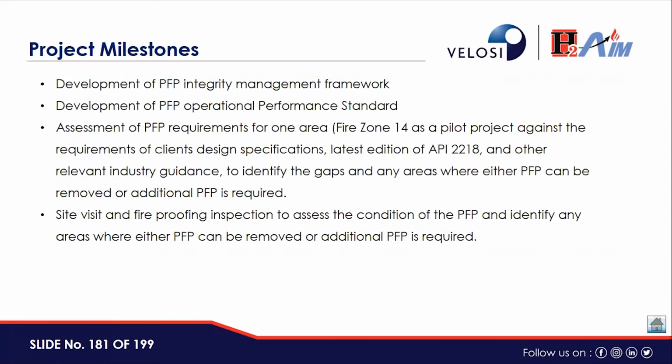These were the project milestones. Development of passive fire protection integrity management framework. Then development of the passive fire protection operational performance standards. Then the assessment of PFP requirements for one area, which we have selected as fire zone 14 as a pilot project, against the requirements of client's design specifications, latest edition of API 2218 and other relevant industry guidance. And then to identify the gaps and any areas where either PFP can be removed or additional PFP is required.